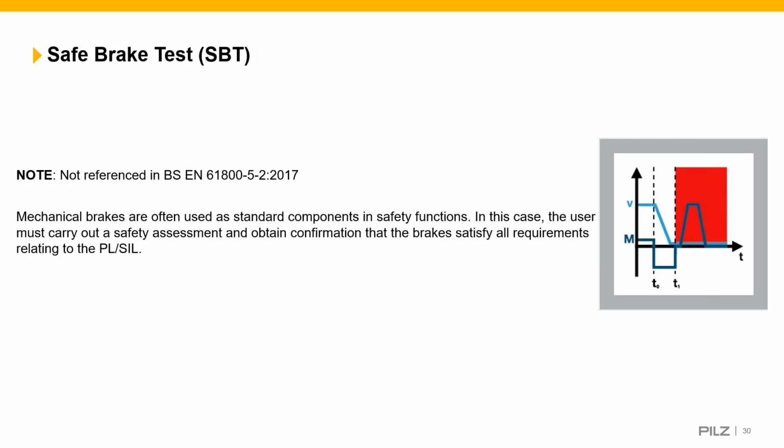So safe brake test. Now, just a note there, it's not referenced in the standard. Mechanical brakes are often used as standard components in safety functions. In this case, the user must carry out a safety assessment and obtain confirmation that the brakes satisfy the requirements relating to the performance level or the safety integrity level that's required. So this is again back to risk assessment. We always say this about just about everything that we talk about, but this is how it should work.